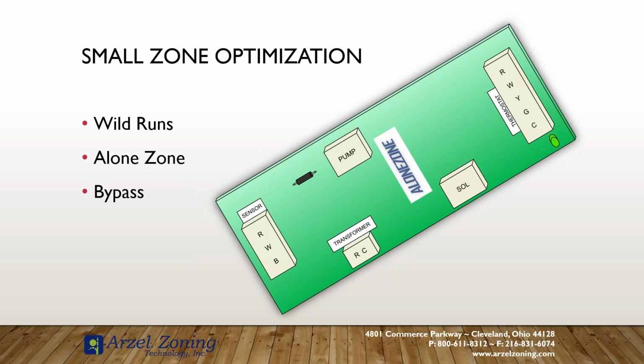The alone zone allows you to damper off that area by itself based on a thermostat control and a duct sensor detecting if there's heat or if there's air conditioning running. So if the thermostat calls for heat, the duct sensor says it sees 90 degrees within the supply duct. It allows that damper to open, satisfies that heating call, thermostat turns off, damper closes, stops the over conditioning.